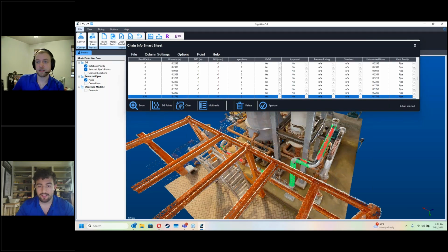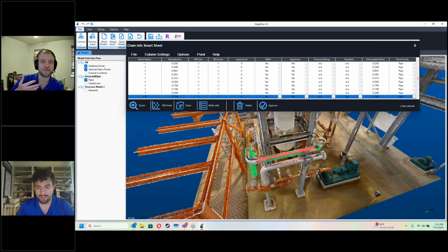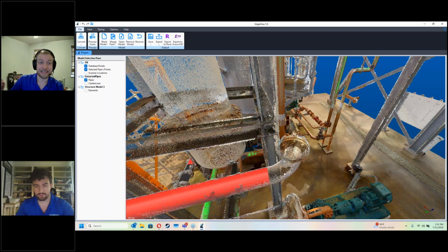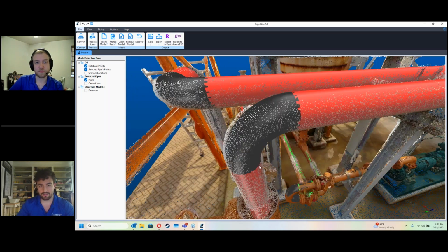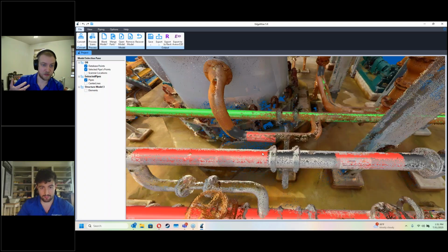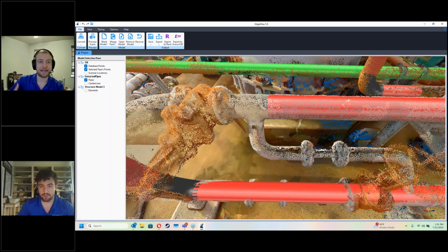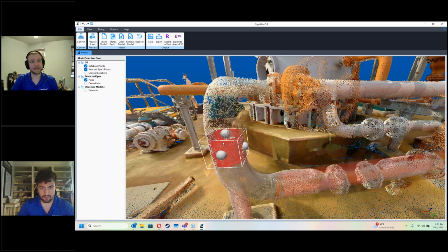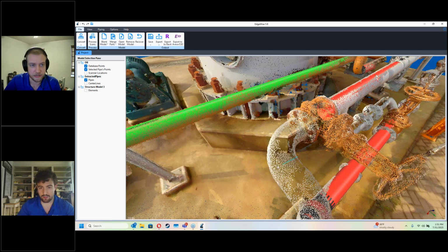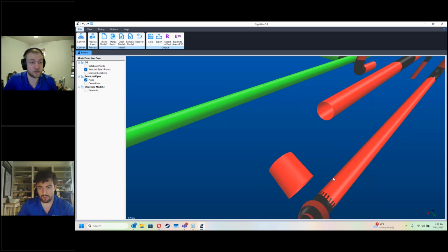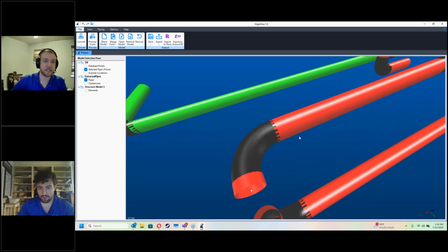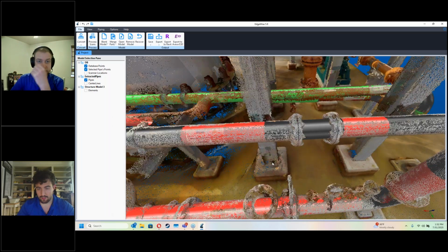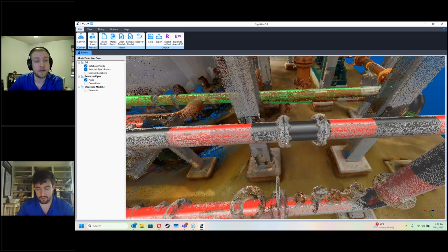Can we use Plant 3D specs? Sort of. We have default specs inside of EdgeWise. Those are mapped very specifically with EdgeWise E3D specs. So the general recommendation for the workflow is to use the default EdgeWise specs, and then in Plant 3D you import with those specs. When you install the Plant 3D plugin, it will add the EdgeWise ASME and DIN specs to your global specs, and you need to add those to the project if it's an existing project after you install the plugin.